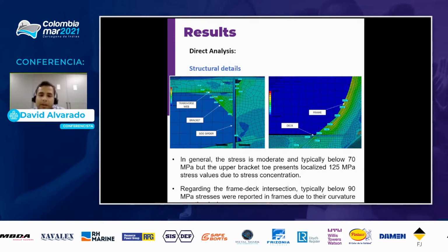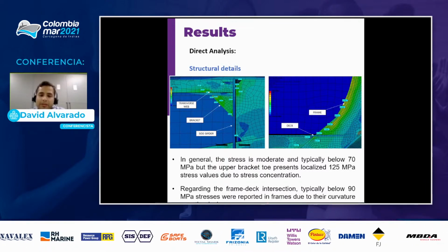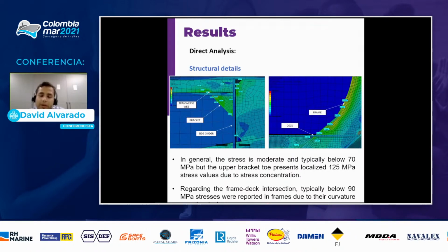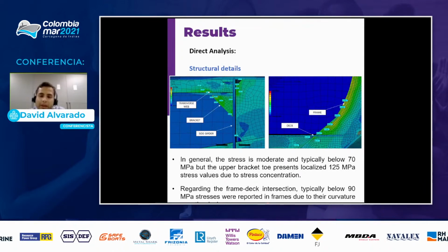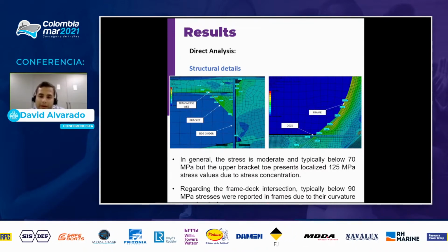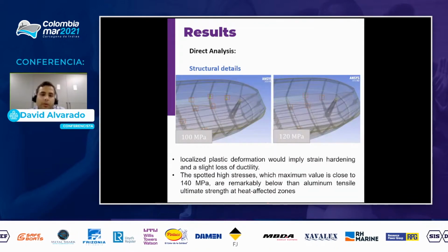To the right, we can see that there is an intersection at the deck of over 90 megapascals at the region with the highest stress, and that is not considered by the standard. The security factor is higher than the one found in this direct analysis.